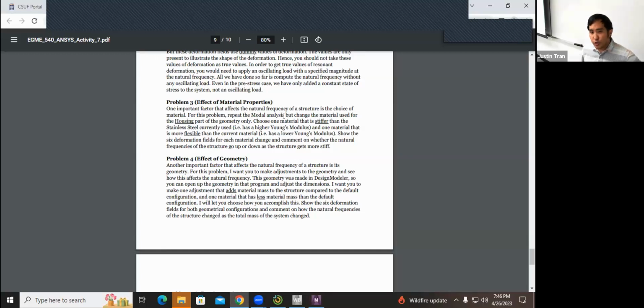Okay? And so I want you to choose a material that's stiffer than stainless steel for the housing, okay? And that's going to be one scenario. And so I want you to rerun the analysis and see what the resonant frequencies are for a stiffer material, okay? And then after that, I want you to choose a material that's more flexible, right? One that has a lower Young's modulus, and then do the same thing. And so I want you to show me all 6 deformation fields and then tell me how the resonant frequencies changed, okay?